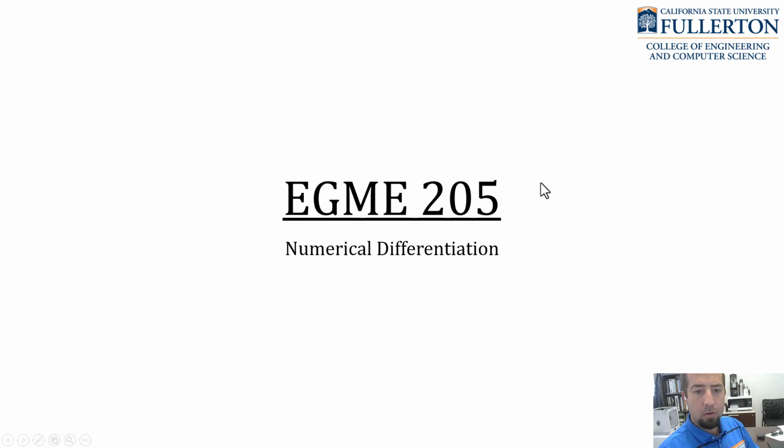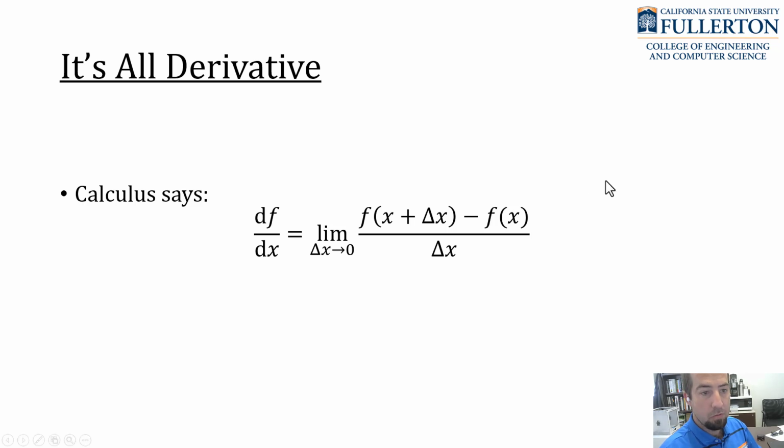A quick method of numerical differentiation based on MATLAB arrays. So in calculus, we define the derivative of some function f of x based on the change in f over some change in x for ever decreasingly sized steps in the x direction.